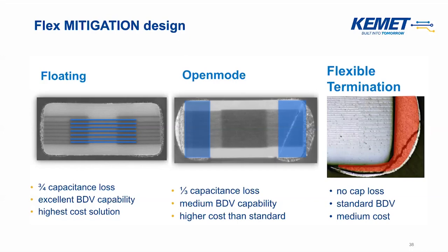If you put a capacitor, let's say 1210, 100 volt, in an oven, it doesn't matter if it has only 1 layer or 100 layers. The same happens for galvanic. If you put the piece in the galvanic in a certain case size, it's always the same workload. But it's the stacking and drying of those layers that makes a difference. A part with more layers definitely costs more in production than a part with fewer layers.